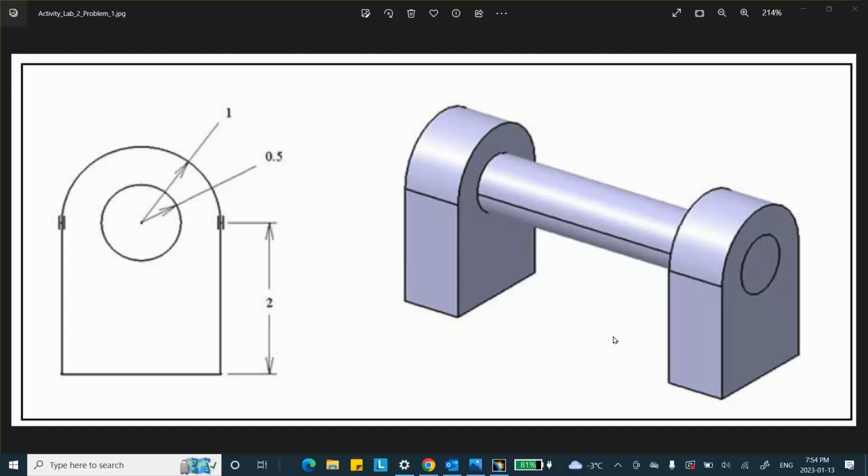And then once you save it, you can say insert an existing component, and basically select the saved component, and it's going to bring it into the display. This is a lot more efficient than just simply copying and pasting. For example, if you have a problem which has 100 bolts and you try to copy each bolt, well, it can be very cumbersome and inefficient.